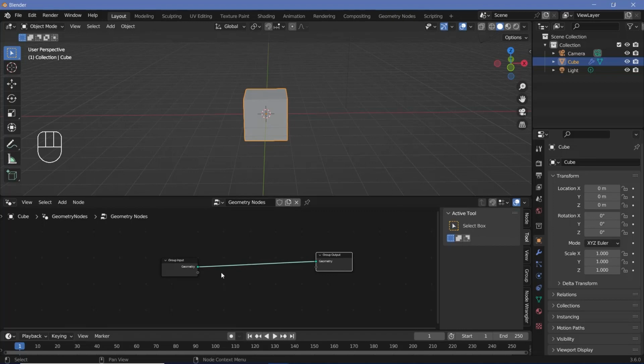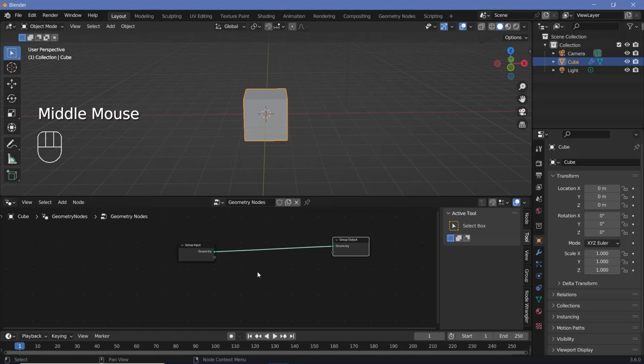So it's going to go to the left, see whatever nodes are there, and for those nodes, whatever's connected to it is going to be evaluated. So it keeps traveling down the chain from the output side towards the input side. Hence, if you use some sort of an information node like position or any other attributes, it'll always give you the position of whatever's there just to its right or whatever it's being connected into. And with that, we have the base knowledge of the working of geometry nodes, and we can actually start off